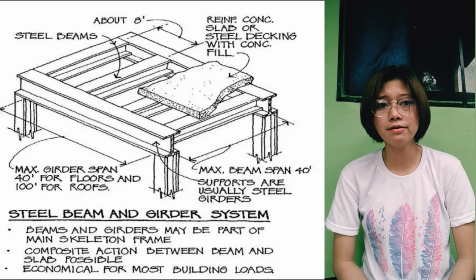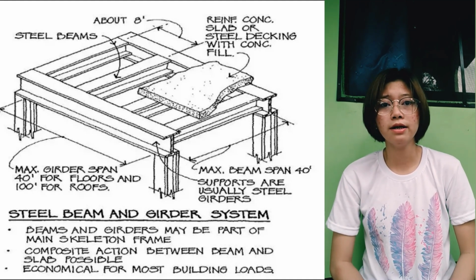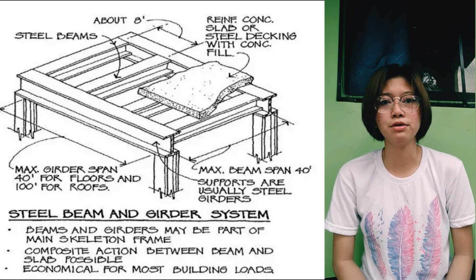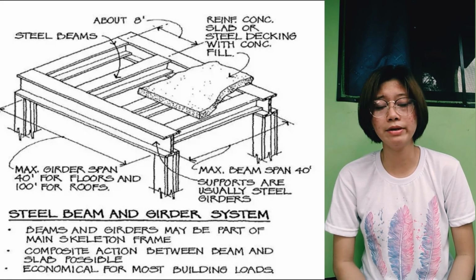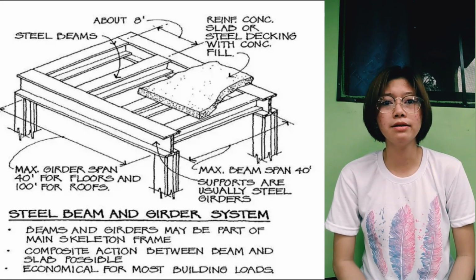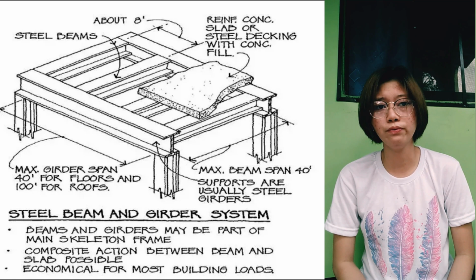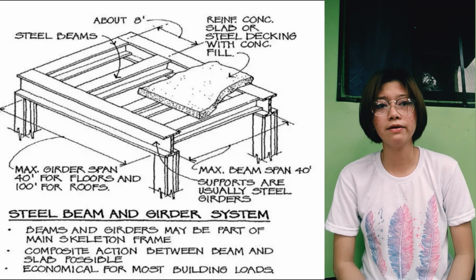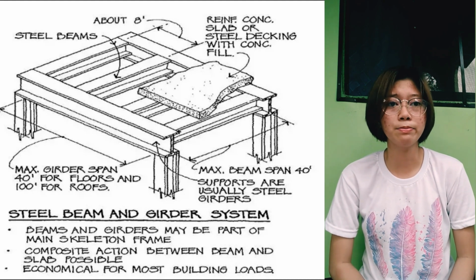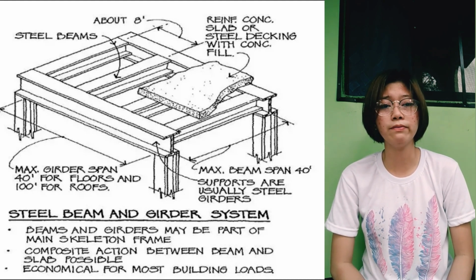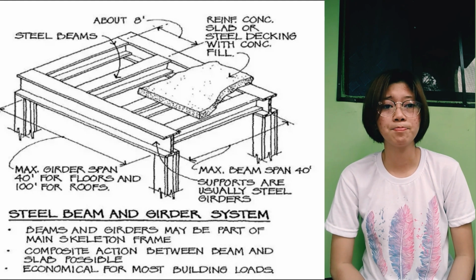The main tensile reinforcement running along the short direction in fully continuous slabs is alternately bent up, usually at an angle of 30 to 45 degrees at the third points of the span and extended over the supports to quarter points of the adjoining span.